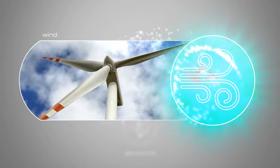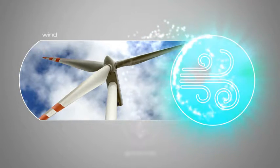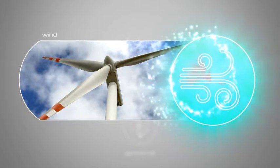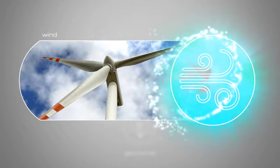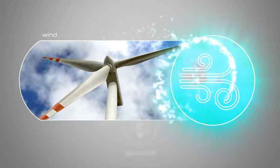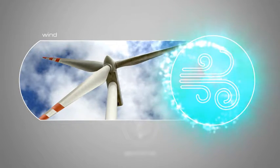The horizontal axis wind turbine is the most common type of turbine used when producing electrical energy. There are two types of horizontal axis wind turbine, upwind and downwind. Upwind are the most common since the blades are positioned upwind of the supporting tower. Downwind turbines have been built, however there's a problem of turbulence created from the supporting tower which decreases the efficiency.